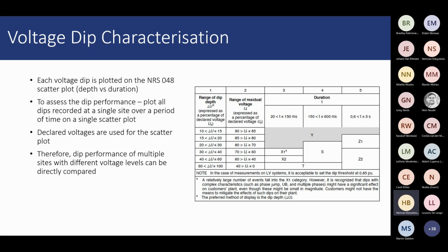Yeah, because you see these IPPs, they've got these apportionments, let's say harmonics, and it's very small values. So then it falls in the noise floor almost, and you then have no idea if that value is actually accurate. And it's not just the magnitude. For the IPPs where they need to prove compliance, the angle also becomes important, and the angle can be shifted due to VTs and CTs. So definitely, I think there's some work to be done here, and some info needs to be shared on this. Okay, thank you for the feedback.